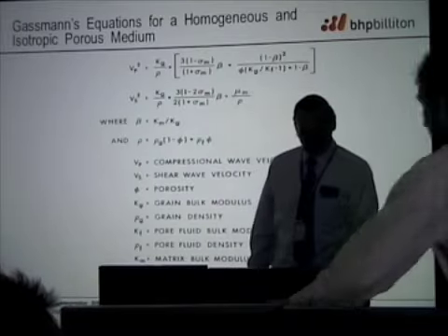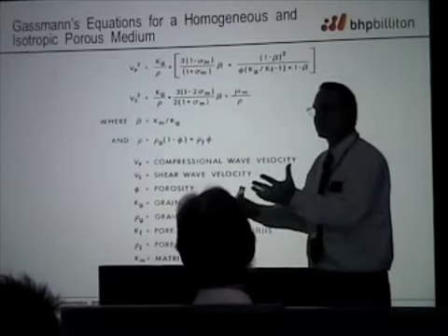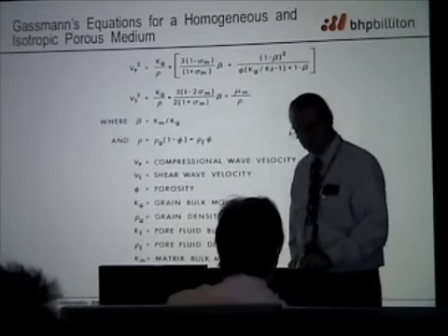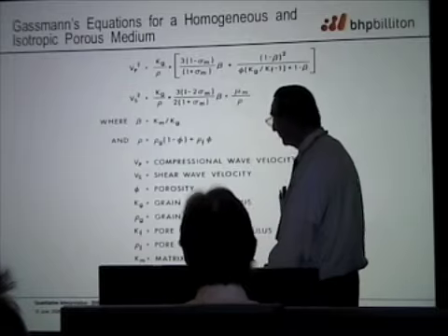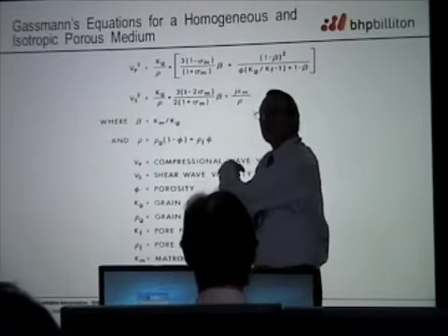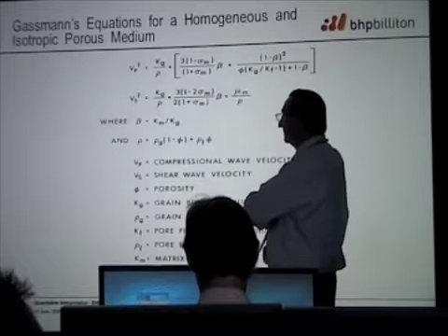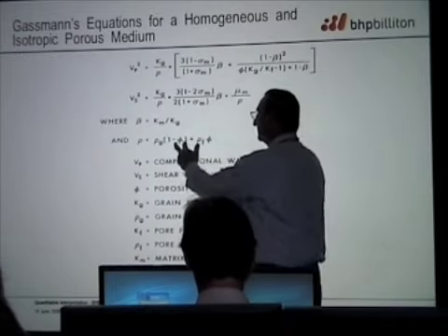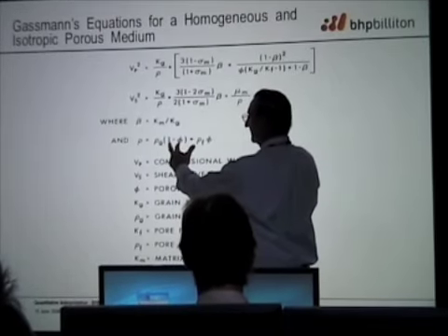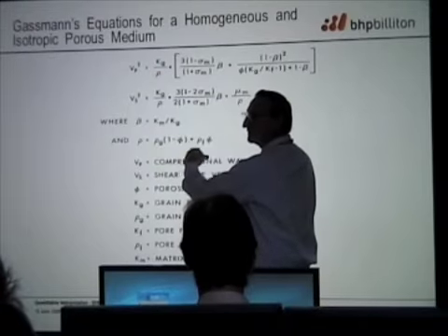Porosity at the sea bottom is like 40% or something. When you first drop the stuff out, in the first few feet, it gets down to a reasonable porosity. So think of porosities in the 30 to 40% range here. Those are the softest sediments you're going to find. Even for that soft a sediment, this thing is 0.6 to 0.7, times 2.65 for quartz.